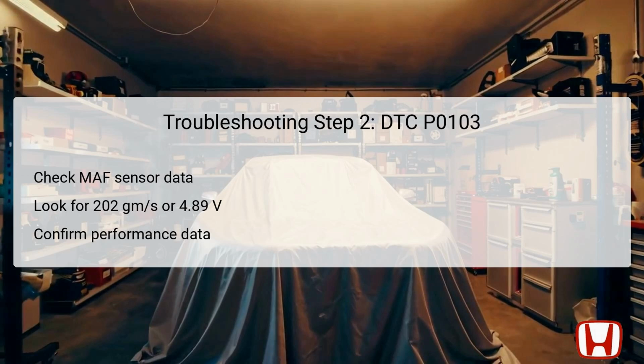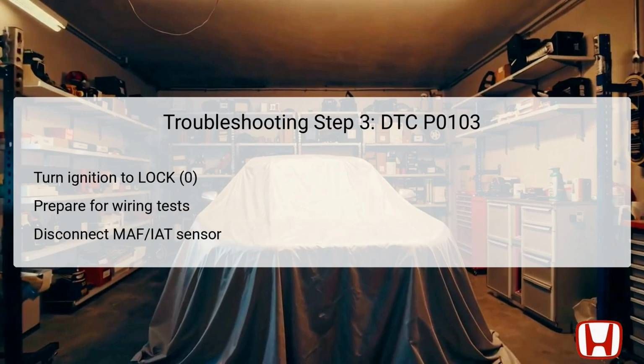If the readings are within specifications, this suggests that the system might be fine, and the next action should be to investigate potential intermittent failures or connection issues. For troubleshooting step 3, turn the ignition switch to the lock 0 position. This action ensures safety by cutting off all electrical power before performing any disconnections or tests.